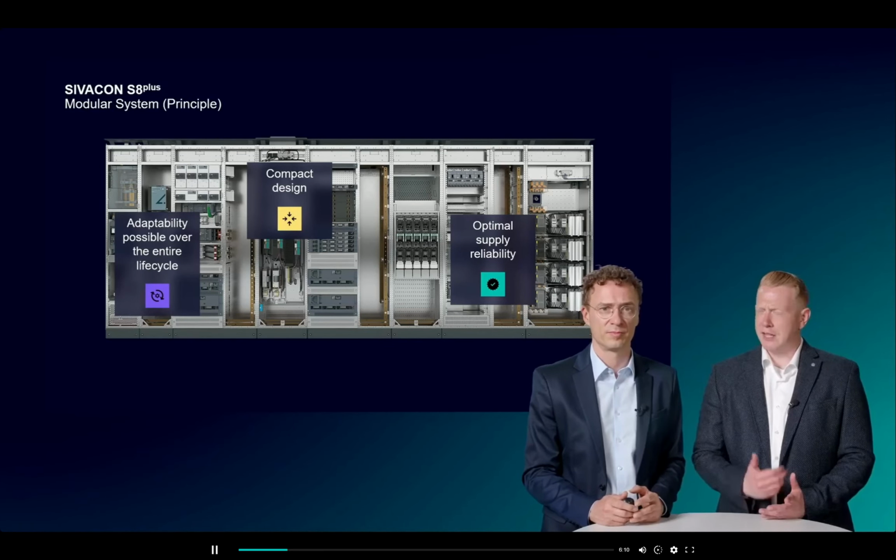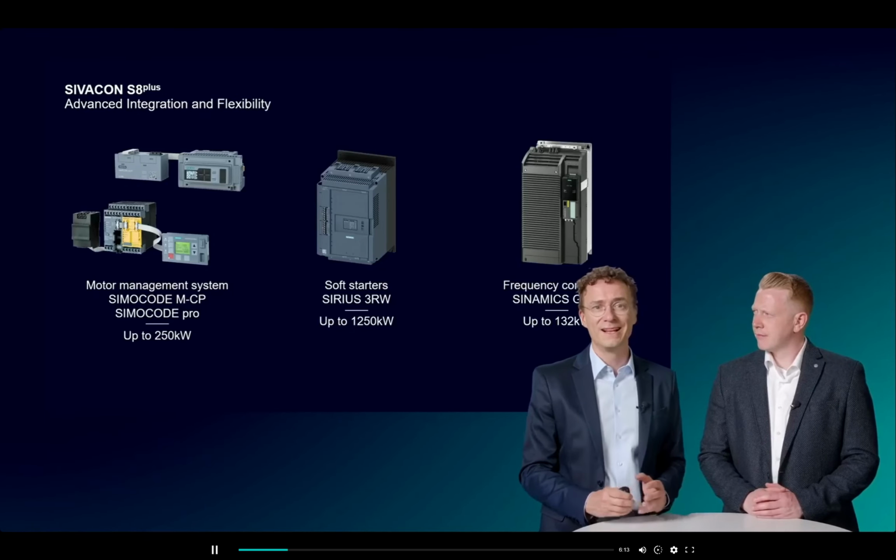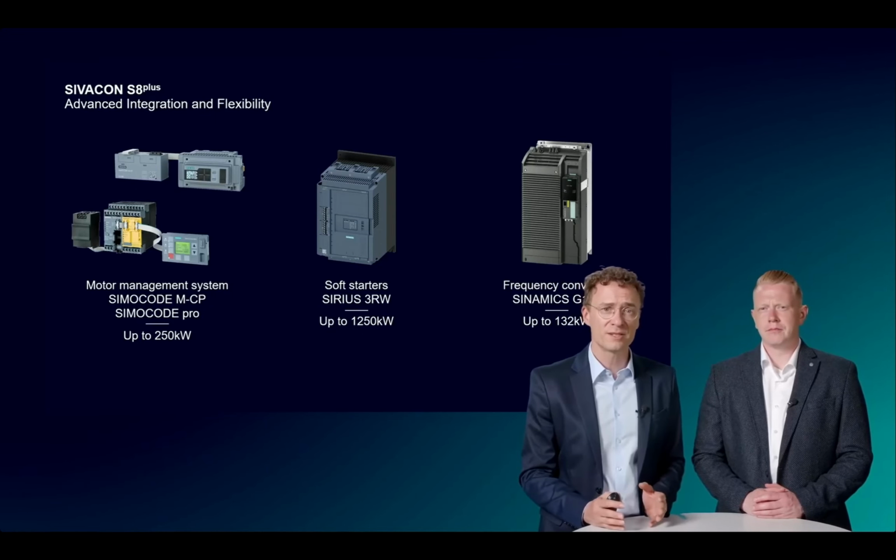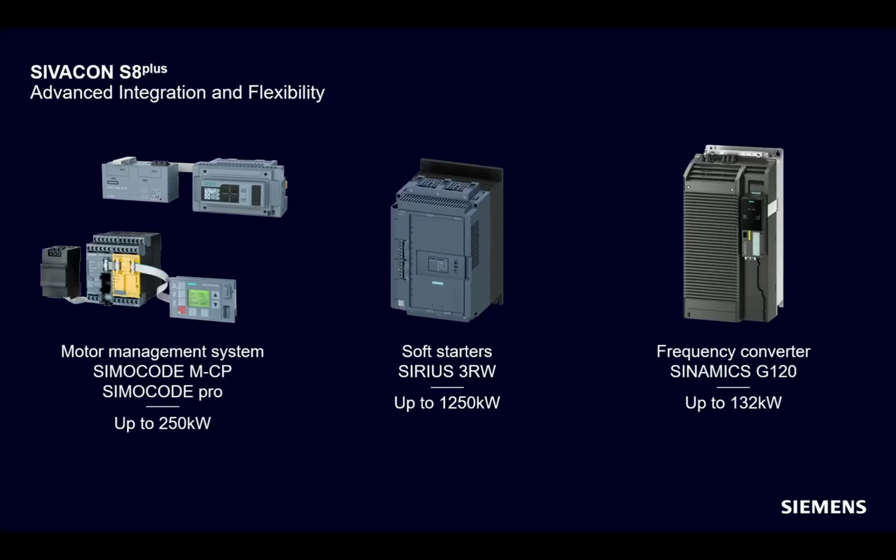Does the same apply to the requirements? The current measurement is, in addition, a bit more tricky in this system case. As you can see here, the suitable current transformer for motor feeders, we can also use in the supply feeder. Large consumers using soft starters or variable frequency drives.